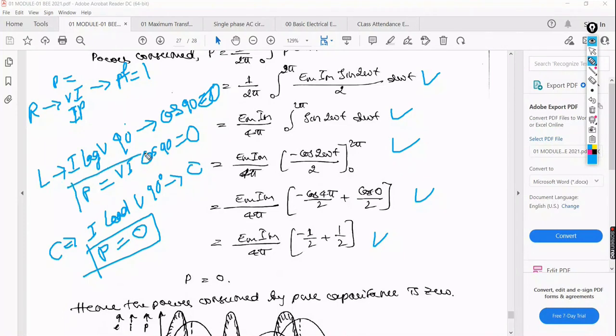Don't forget at all. What is the power equation for pure resistance? The product of the RMS value of the voltage and current, because cos phi is equal to 1. Is this clear now? In phase, out of phase. Remember it. In case of inductance, current will lag voltage; in case of capacitance, current will lead voltage. For pure inductance and pure capacitance it is by 90 degrees. For resistance, current and voltage are in phase.